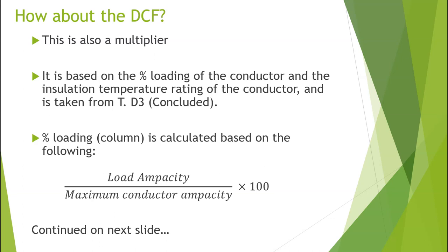So for example, we would go to table 2, assuming that we are running copper conductors up to this point, and we would use our number 10 AWG that we've been looking at so far and go across at number 10, and then take our maximum ampacity from the 75 degree column, because we're working in this video from the assumption of a 75 degree termination temperature.